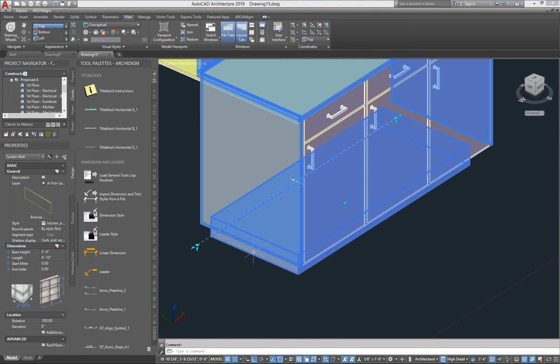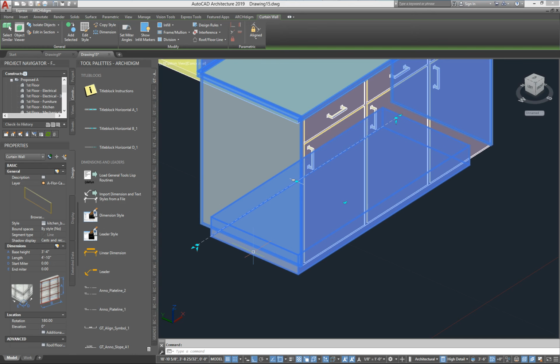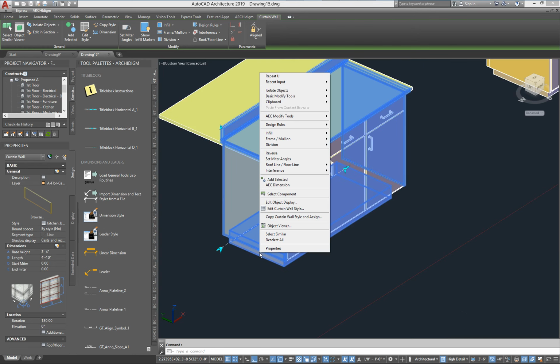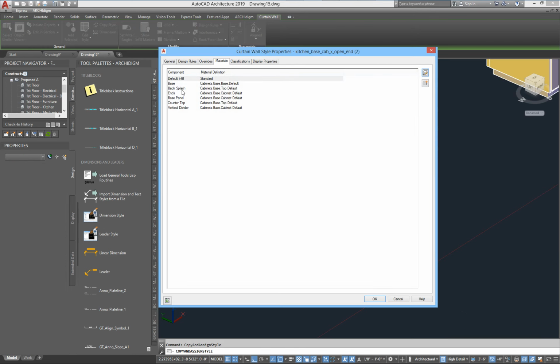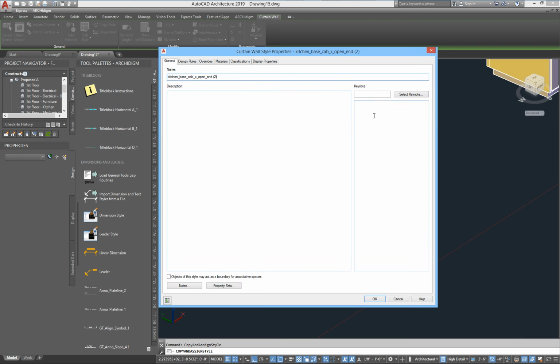So what I would do here is I'd go ahead, grab the G2 cabinet, standard base cabinet, right click, do a copy, and I would probably indicate here that I might put the word in island cabinet, something like that, so that I know that it has no countertop or something.